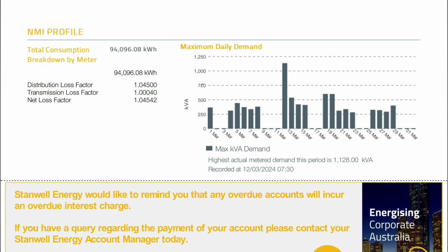So if we can have some peak demand management control strategy and the BMS says, whoa, hang on, it's a warm weekend, the plant's not running, it's a warm Monday, it's a public holiday, it's a 35 degrees Celsius day on Tuesday, we're definitely going to hit the peak.